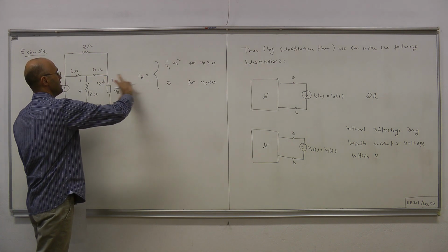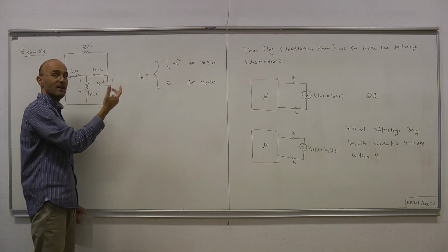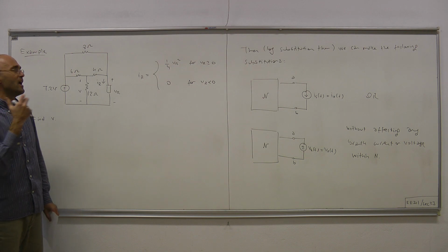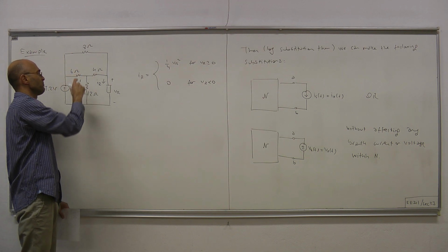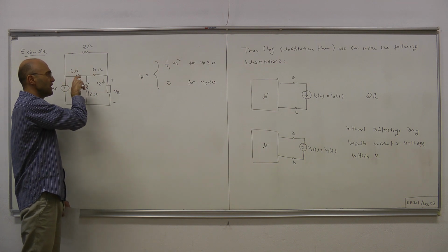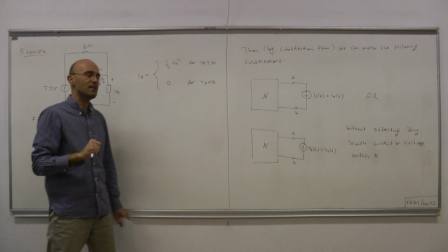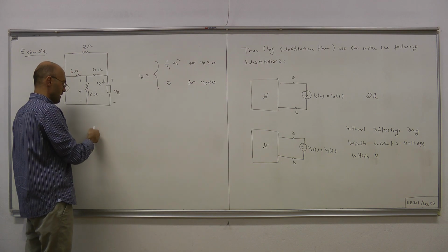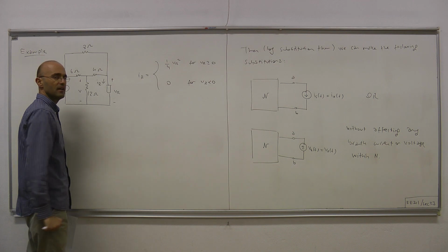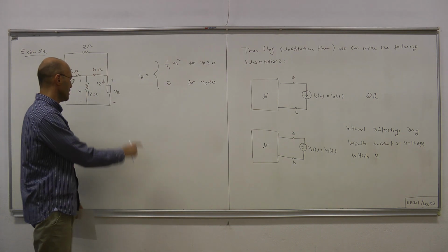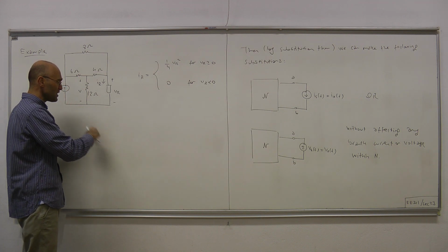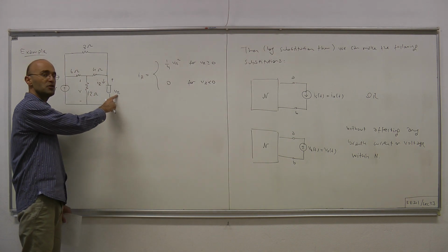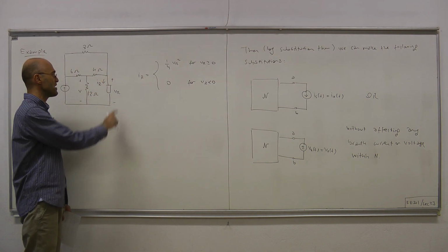So just take this out and leave this as an LTI one port. Figure out the Thevenin equivalent representation for that LTI one port, and then replace this not so simple topology with that simpler Thevenin equivalent circuit topology. In that case, we have the topology that we worked with in the previous example: a voltage source, an LTI resistor, and a nonlinear resistor. Using that very simple circuit, we obtain the equation to be satisfied by the voltage, and then from that equation, we obtain the voltage.